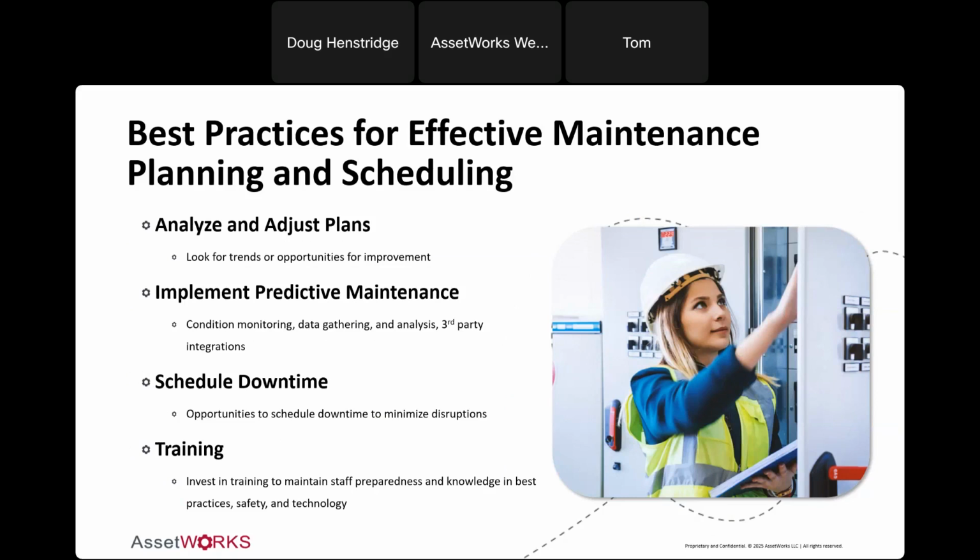The other thing to start looking at is predictive maintenance. How can we start getting ahead of things that are failing, right? Are we noticing vibrations in equipment that shouldn't be there? Are we seeing that maybe filters are more full or more clogged, or catching more dust and debris than we would normally expect? Get out in front of this, because that may be indicative of another problem, or it may simply mean that you need to modify your schedule to get to it more quickly, or sooner, or more frequently, I should say.